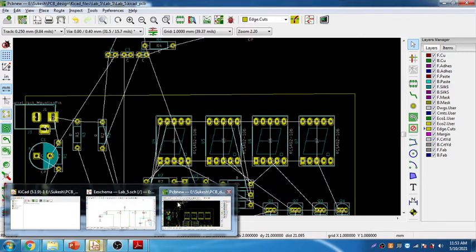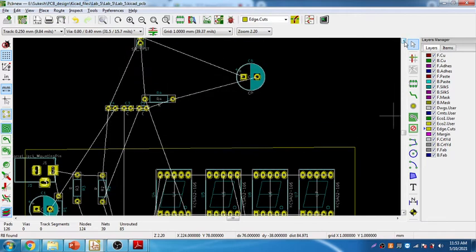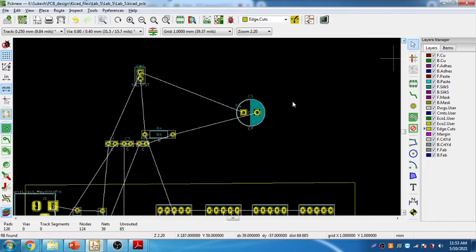Okay, I'll continue. It's almost 11:53, so I might have to stop somewhere. This process takes time. If I have to do PCB routing very well, then the placement is very important. How you place a component, where you place a component, and all the tracking should be nearby. Otherwise, it will make very lengthy tracking. So you have to go with the double layer or single layer, and that again becomes difficult. So what I suggest is I will complete this here.